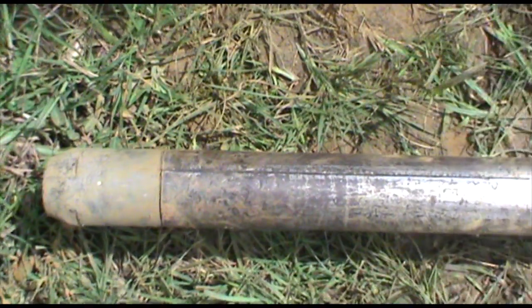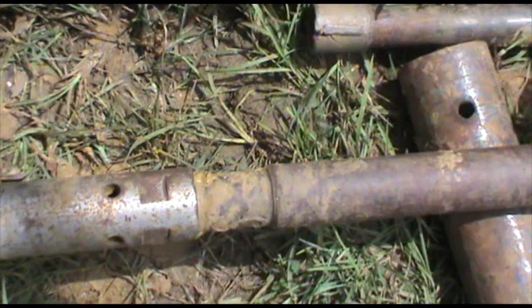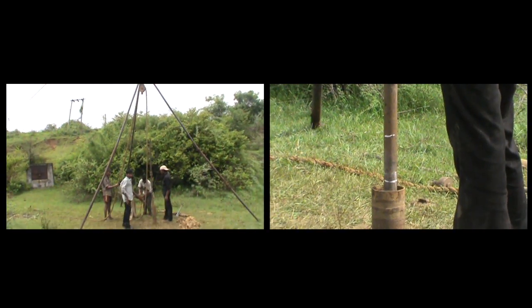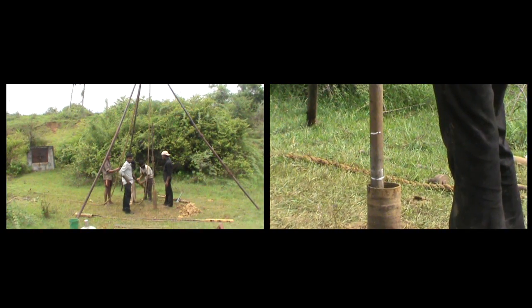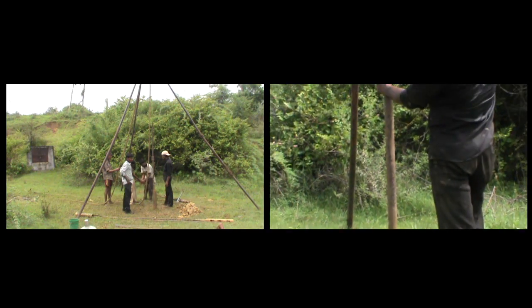So next up, we have the standard penetration test. Well, it is an in-situ test and very famous amongst geotechnical engineers. The origins of this test can be traced back to 1920 as well. The test involves driving a standard split spoon sampler into a soil stratum at a required depth. The sampler is driven into the soil by a standardized drop hammer.